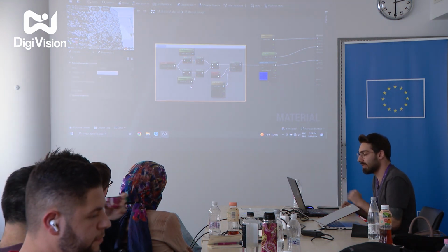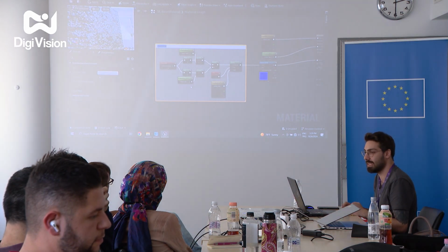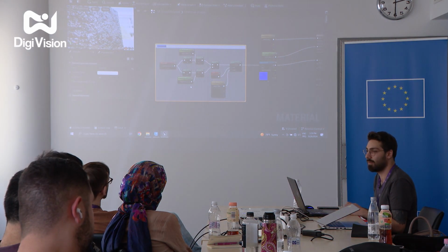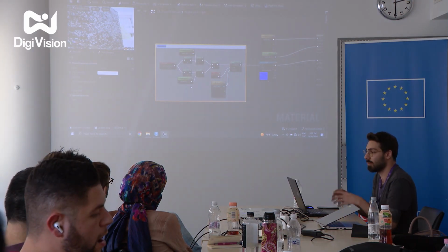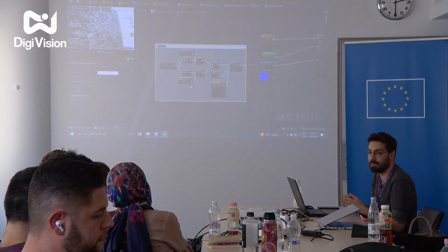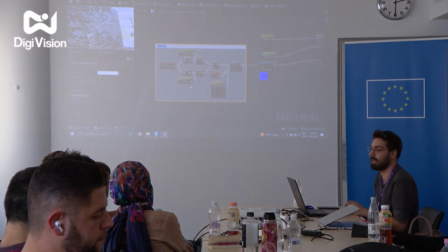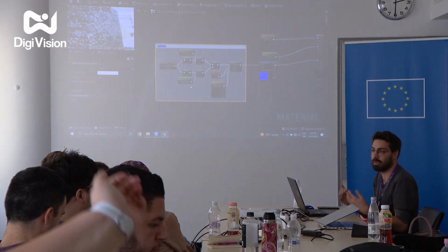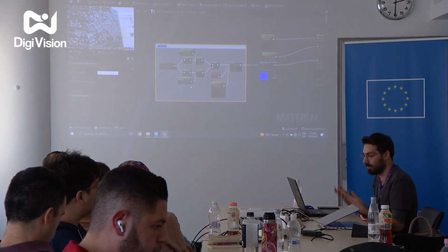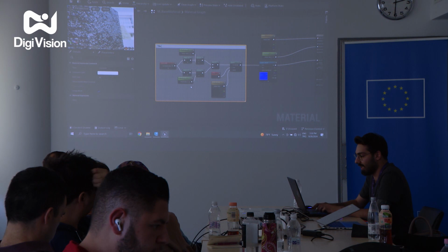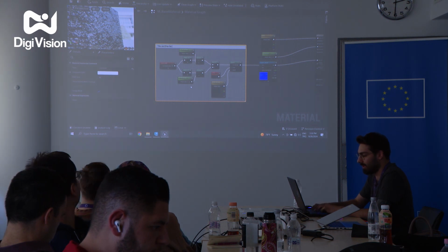You can press C to add comments and type what your calculation is, what the point of these nodes is. For example, in here we just manipulated the UV, tiling the texture and panning the UV. So we can simply type tile and pan for the normal.